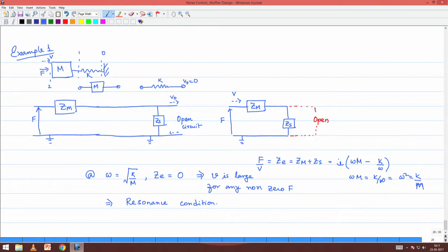So, now for this very same system, that of a spring mass system, we will analyze the transfer matrix method. Accordingly we have 3 stations which are defined as 0, 1 and 2 in this diagram. So, what we need to do is relate the forces and velocities between each of these successive stations. Between 0 and 1 we understand it is going to be a spring element.